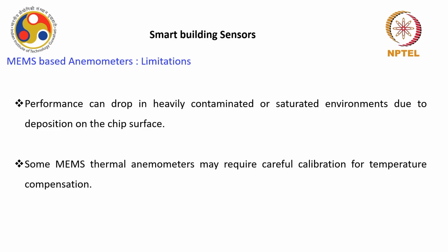There are certain limitations also, like performance can drop in heavily contaminated or saturated environments due to deposition of these contaminants from the ambient on the chip. Some MEMS thermal anemometers may require careful calibration, particularly for the temperature and pressure compensations.